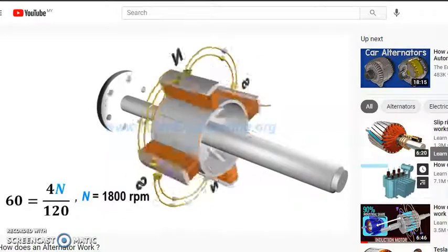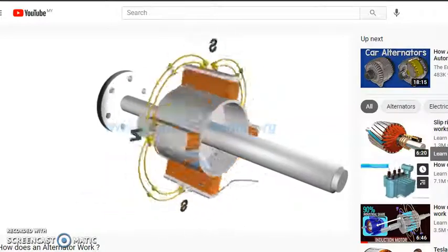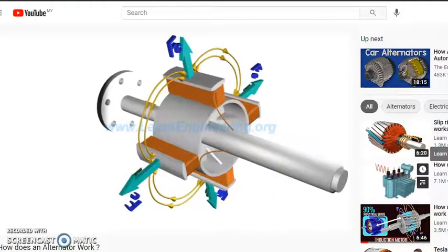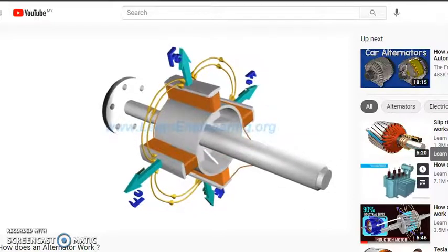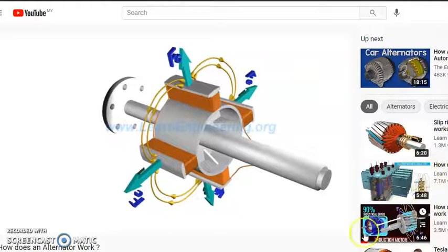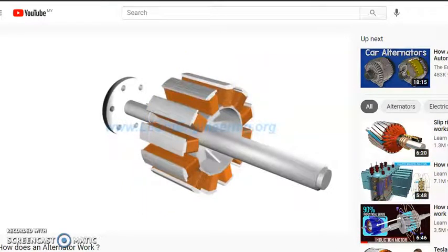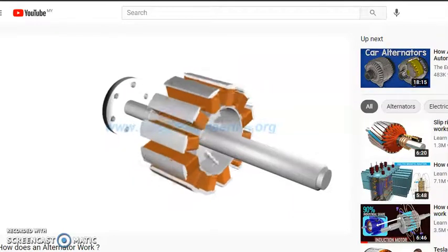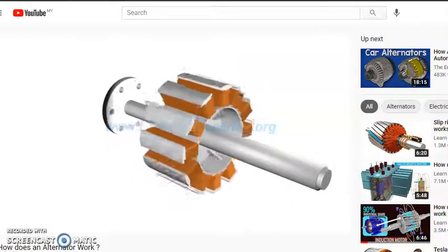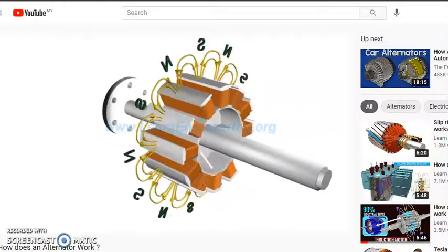Such a huge RPM will induce a tremendous centrifugal force on the poles of the rotor, and it may fail mechanically over time. So salient pole rotors generally have 10 to 20 poles, which demands lower RPM. Or, salient pole rotors are used when the prime mover rotates at relatively lower RPM.